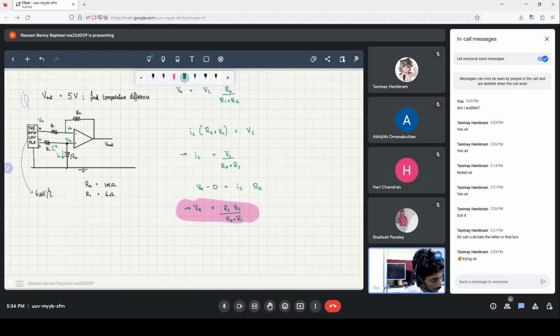Okay, so we just said that we have found VA. Even though we have found VA in terms of all these terms, I'm not going to write it all out; it's easier to just keep it as VA for the time being. By the principles of operational amplifiers, this junction will also have the same potential. Therefore, this junction is also at VA. Since that junction is at VA, and we know this part's at VH, we can find the current here. We'll call this current IH.